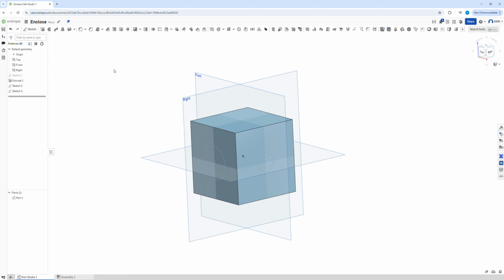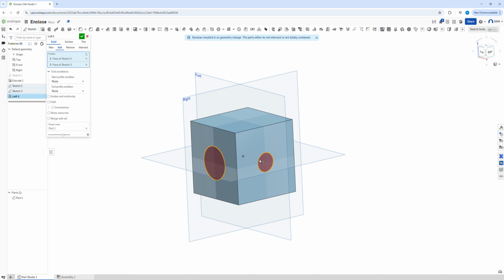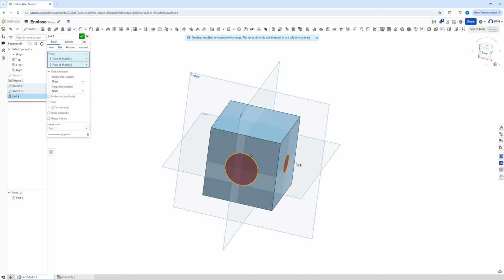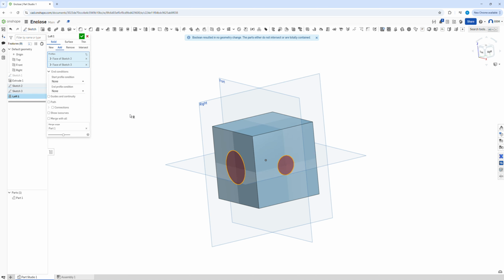So I'm then going to go up and click on loft. Profiles, we want this profile. Sorry, that's the face. We want the circle and this circle. Now, in terms of how it's actually working, it's probably going straight through, which is not ideal. So maybe we want to change this with normal profile 2. Potentially the sizes are wrong. We will see. The actual issue is the fact that we're not removing anything. Okay, so we actually want to take away material rather than add.